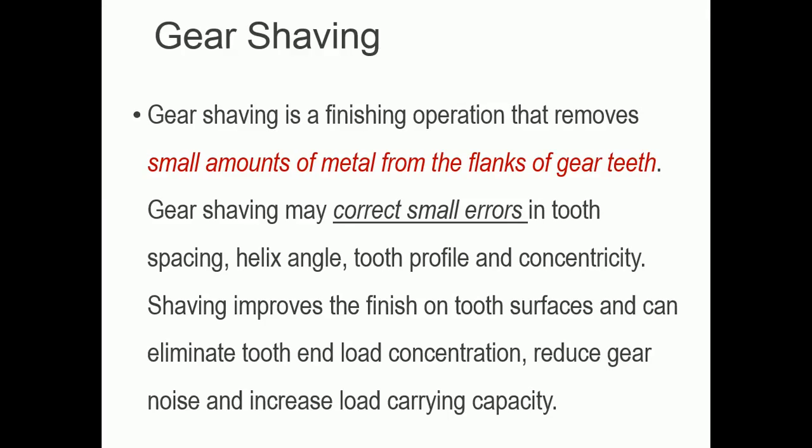Gear shaving may correct small errors in tooth spacings, helix angles, tooth profiles, and concentricity. Shaving improves the finish on the tooth surface and can eliminate tooth end load concentrations, reduce gear noise, and increase the load carrying capacity. These are the gear shaving applications.